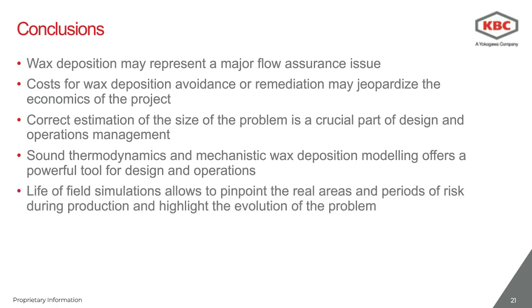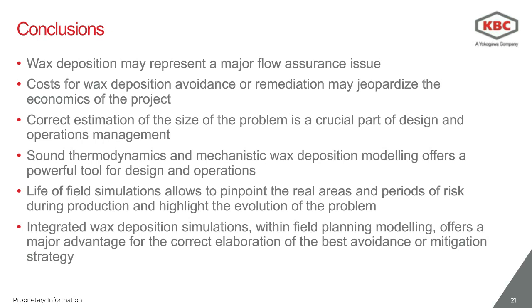We've seen that the life of field simulation allows us to pinpoint the real areas and periods of risk during which the production may be affected by wax deposition. And because this is an evolutionary asset, the effects of variations in various conditions of the production are going to affect the severity of the wax deposition problem. We've shown that having an integrated wax deposition model within the field planning modeling tool offers a major advantage for the elaboration of the best avoidance and mitigation strategy.